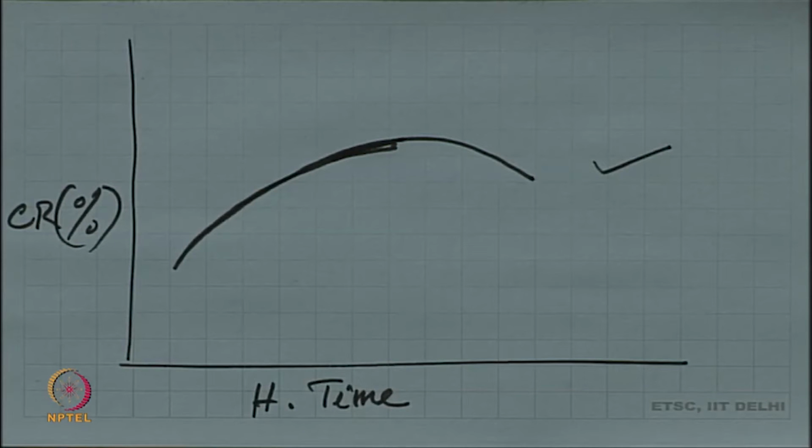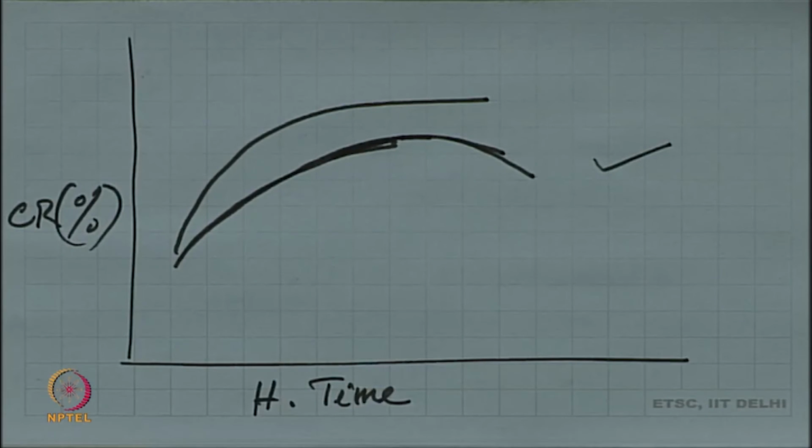It should increase because you are allowing time for breaking of intermolecular forces and rearrangement. The more time is allowed, the more of this can happen, and therefore the free energy is going down, getting into a more stable state. More stable state means more set, and that means a better crimp rigidity, right. Why does it go down then? It should keep increasing, or could have become constant when there is no scope for further improvement in, let us say, crystallization. Why does it decrease?